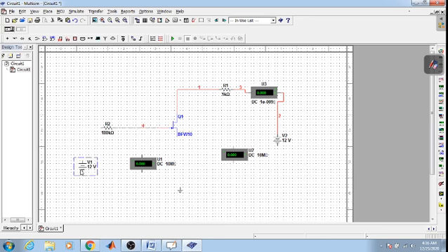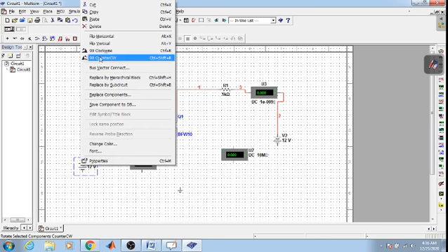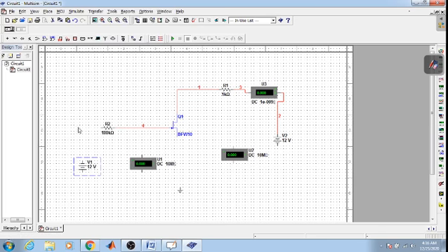Now you observe here, this should be reverse biased. So flip vertical. So this is your negative terminal and this is the positive terminal. Negative terminal will be given to the gate and your positive terminal should be given to the ground. So this is a major difference between MOSFET and JFET. Now you connect this source to the ground and connect this negative to the ground.